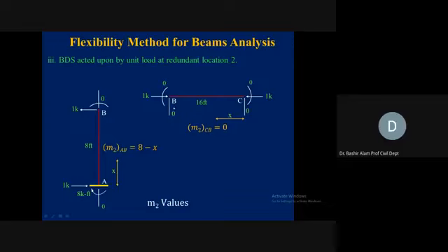The joint should be in equilibrium, so vertical 0, horizontal rightward 1 kip, horizontal leftward 1 kip, moment 0. Let's put this AB in equilibrium: 0, so 0, 1 kip left, so 1 kip right. Now this 1 kip is causing a counterclockwise moment of 1 times 8, which is 8 kip-feet counterclockwise, so it should be balanced by 8 kip-feet clockwise.